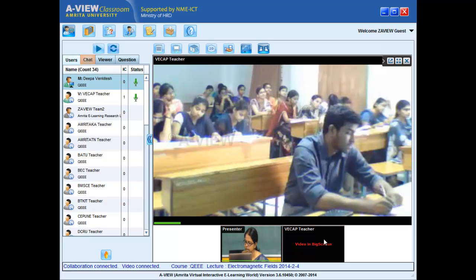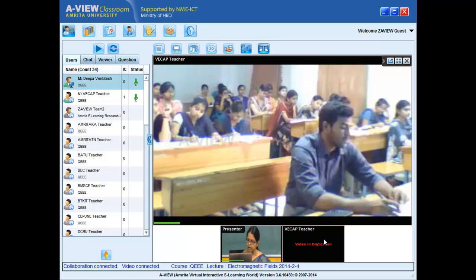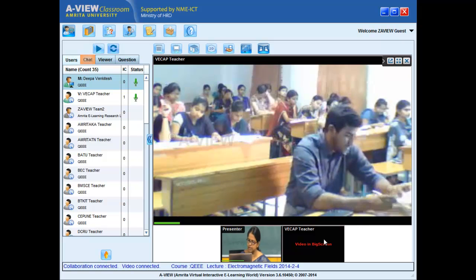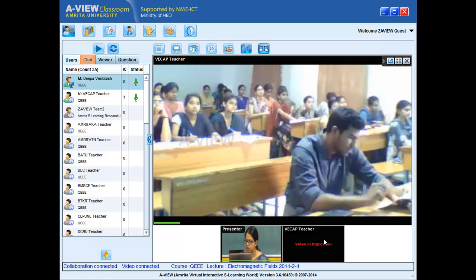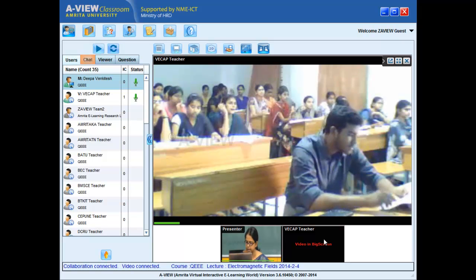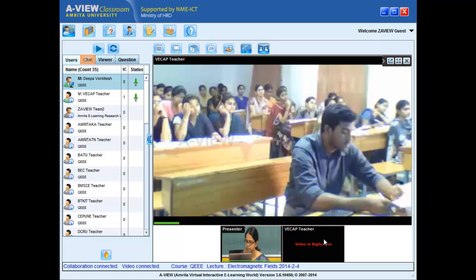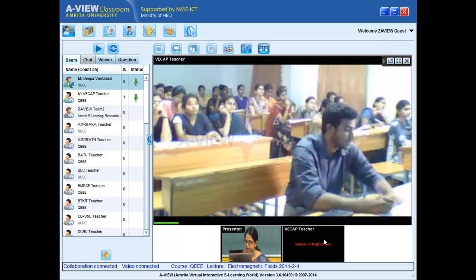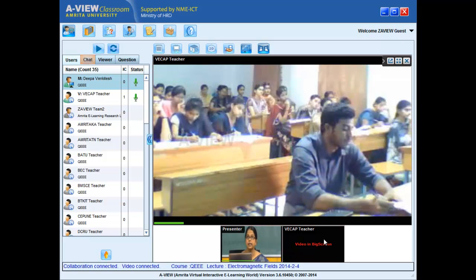Similarly, this would be V(z plus delta z, t). So that is the current leaving through this branch. We wrote the current leaving through this branch as the sum of these two, and you also have the current leaving, I(z plus delta z). So I can complete KCL with I minus, because this is current leaving, equal to 0. This is my second equation.